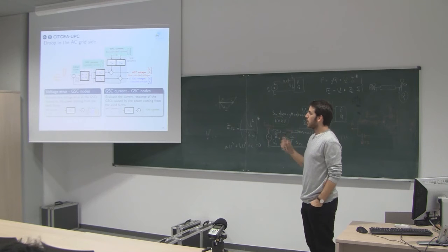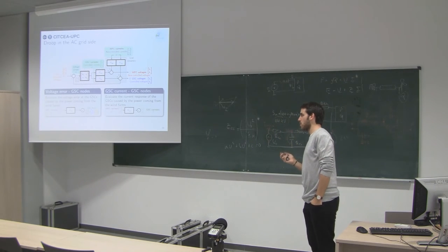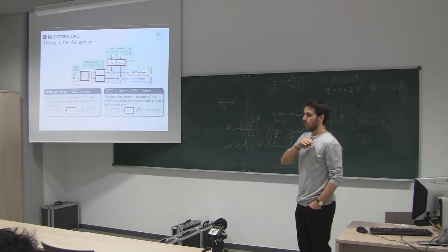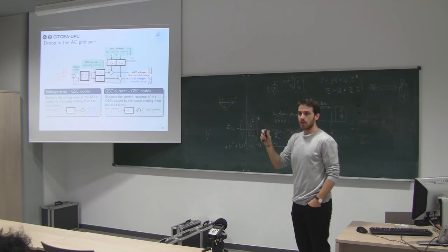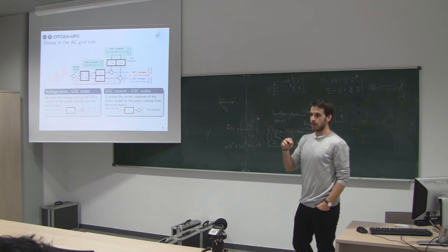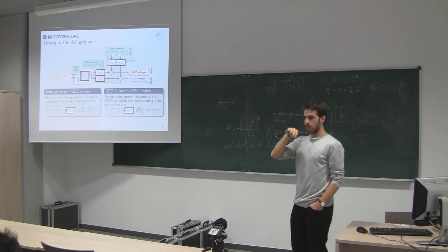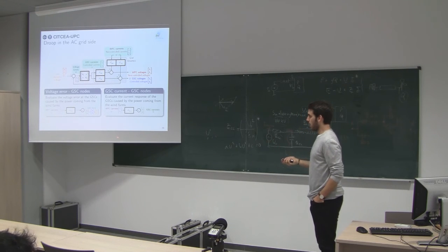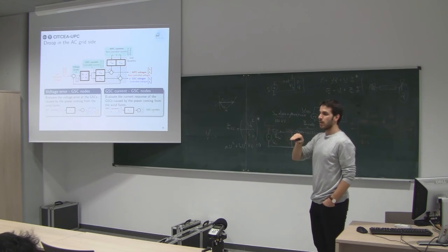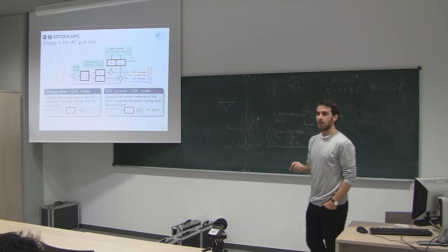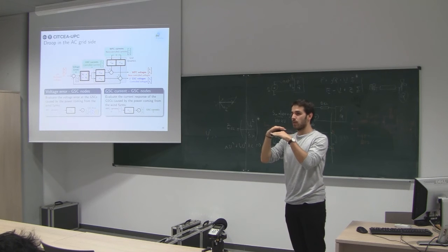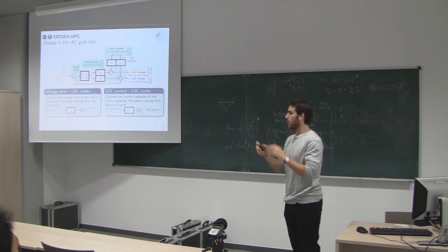So I decided to analyze two different transfer functions. One was related to the wind farm current. As soon as a wind farm changes its current, what's going on with the error? Do I see some large peaks on the error? Do I see a smooth transient? And then I wanted to see what's happening with the grid side current as soon as you have some wind farm currents coming. I wanted to check that to avoid overcurrents on the converters.